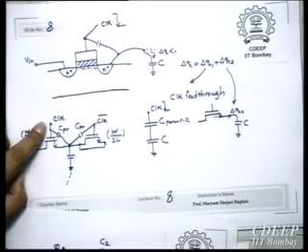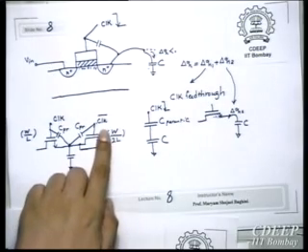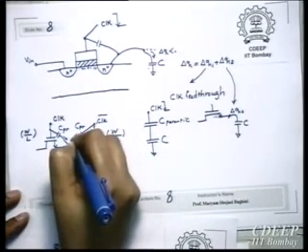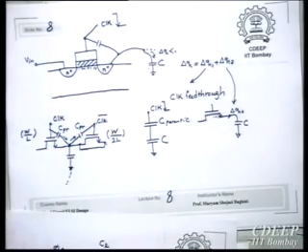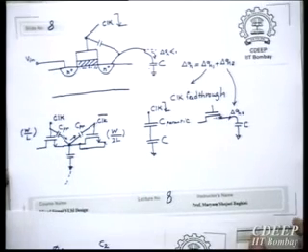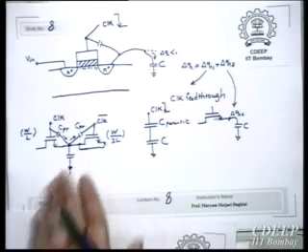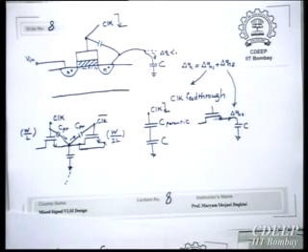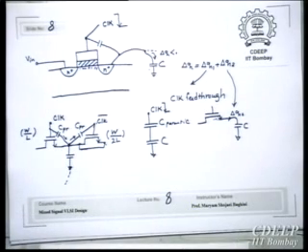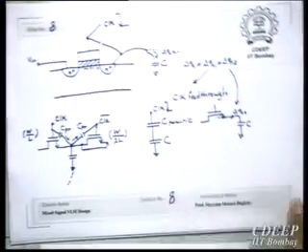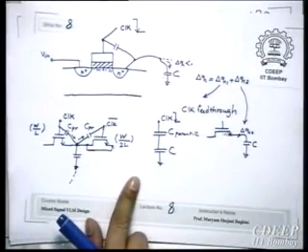Now when clock goes from high to low, clock bar will go from low to high. Therefore the charge which was coming here will now be absorbed by this and nothing goes here. So putting a dummy switch, for example, is one of the ways to avoid this clock feedthrough. Another way is to make this capacitor quite large compared to these parasitics. Therefore it is always preferred to connect everything to ground. Okay, so this is clear.